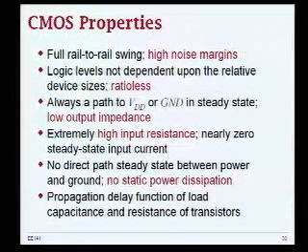In steady state, you always have a conductive path to either VDD or ground, so you have a low impedance output, which is really good for noise robustness, and it's very good against crosstalk and those kinds of noises. You have extremely high input impedance because no current flows through the gate, and there is no path in steady state between power and ground because you are either at VDD or ground, so no static power dissipation can exist when your VDS is equal to 0.